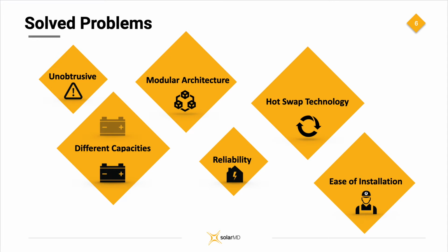No modular architecture. Most larger batteries were sold as one unit. This makes logistics in developing countries a nightmare. There are also no load sharing capabilities with that configuration. In other words, if the unit has an internal fault, the whole unit is down. Hot swap technology. We found that most batteries had over-complex battery management systems and internal components that were not easily accessible, thus making it impossible for a qualified technician out in the field to replace any component remotely.